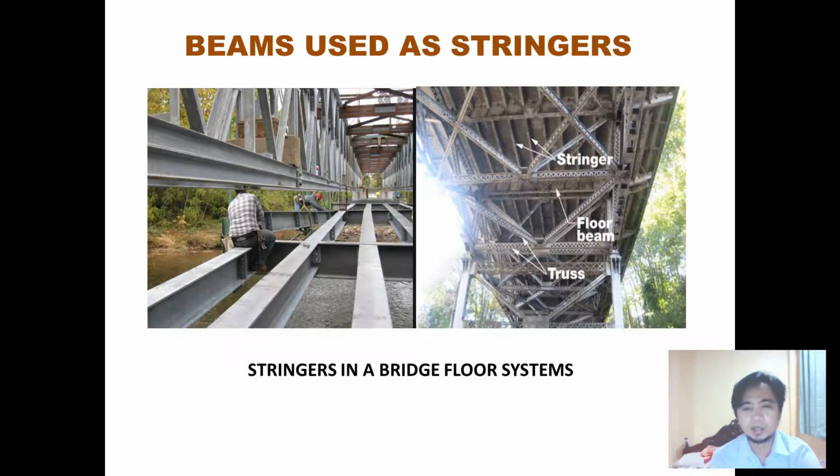That is why when we analyze a bridge truss, usually the load is set at the joint, because by principle of superposition, those transmissions will finally be transmitted to the bridge truss itself.